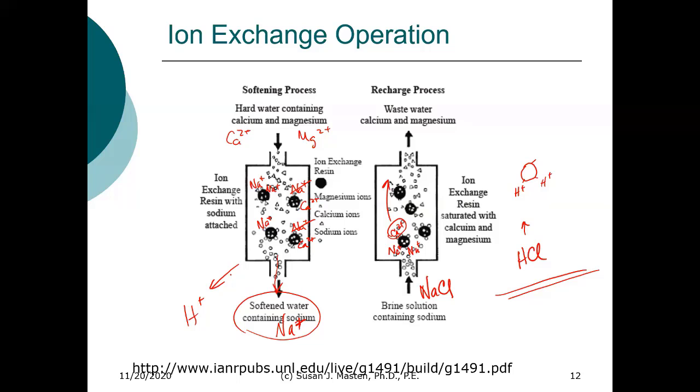If you don't have sufficient alkalinity to buffer the system, you're going to end up with treated water with a low pH. So we could, but we have issues with safety, and we have issues with decreasing the pH and resulting in increased corrosion, which also can be a safety concern because of the release of metals into the water.